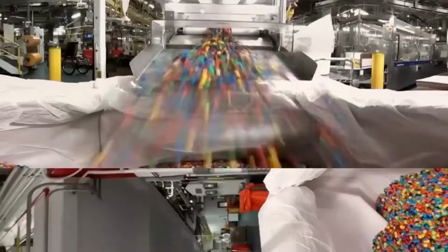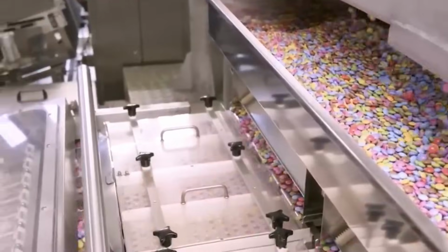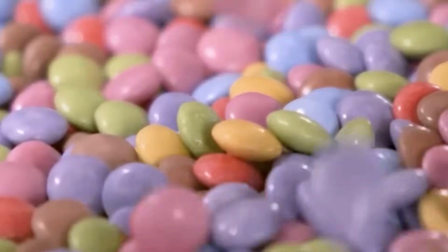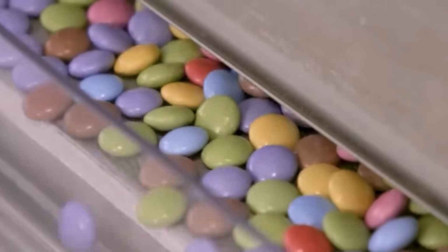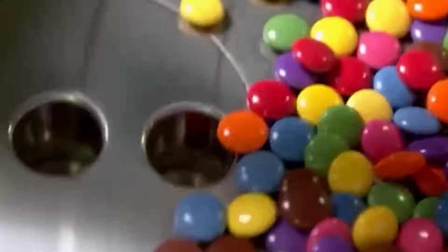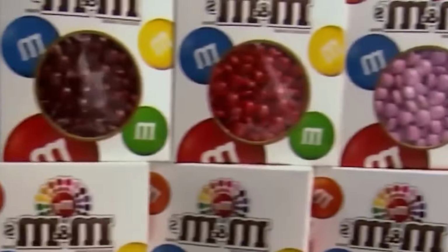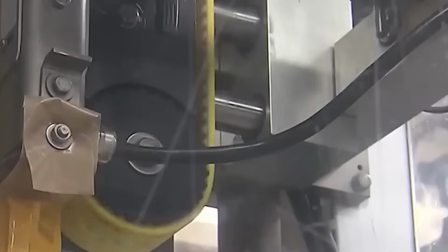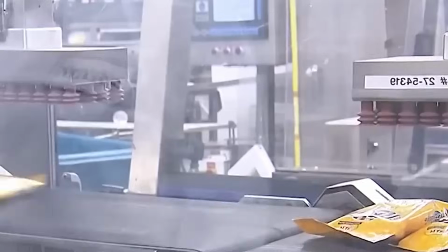As the sugar shell builds, the product passes through a smoothing phase where the surface is hydrated and then gently polished with microcrystalline wax. This polishing provides the final product with its gloss and protective coating. A final tumbling phase is conducted in pans lined with polishing baffles and anti-static systems to prevent buildup on the interior walls and ensure free movement of the candies. After polishing, M&M's caramel units are conveyed to the grading station.